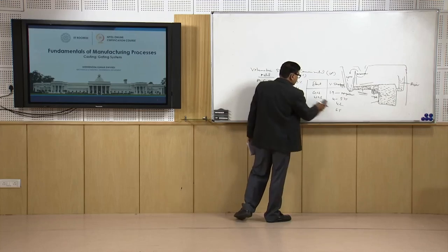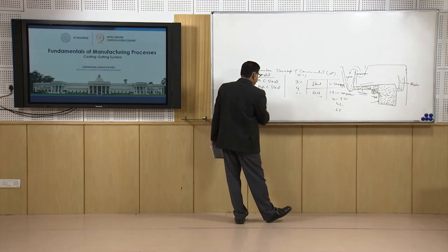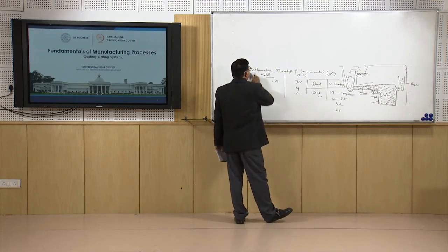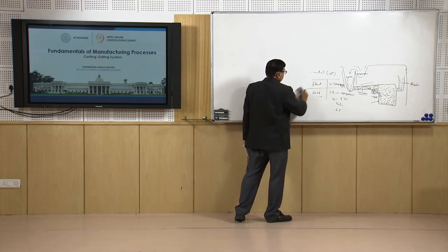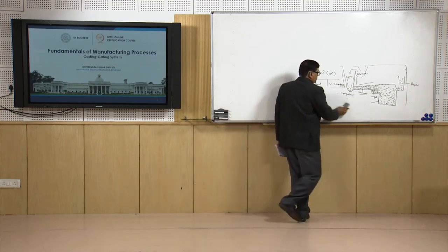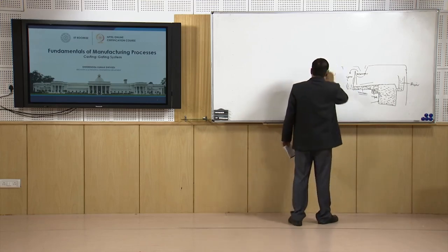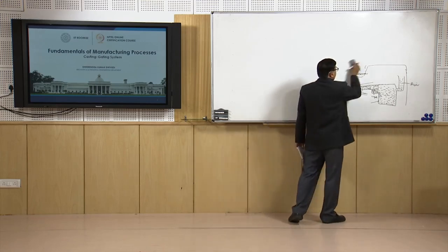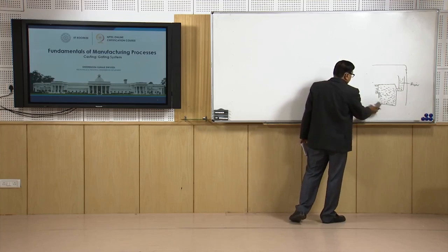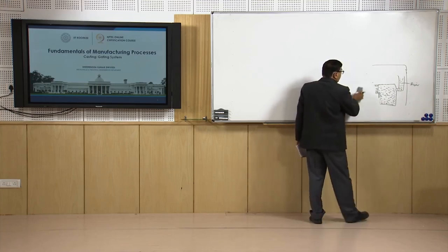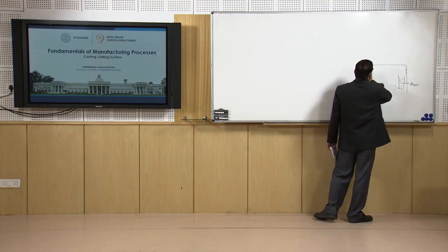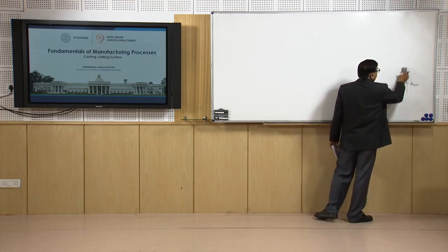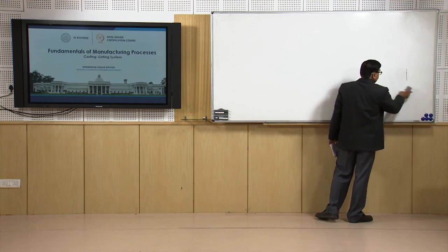Depending upon the metal to be processed by the casting route, the riser is to be designed properly, so that it can deliver the required molten metal to compensate the shrinkage related with the liquid to solid state transformation.